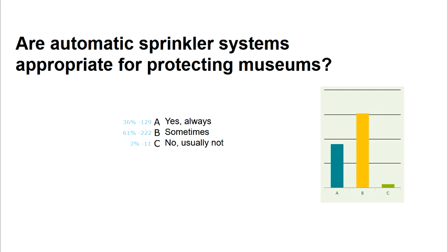In some areas in our museums, we've actually installed copper piping instead of steel. The water in the copper tends to stay cleaner. But one thing to keep in mind is that if you have a fire large enough to activate a sprinkler head, probably your last concern is going to be how clean the water is. Your first objective is just to control the fire.